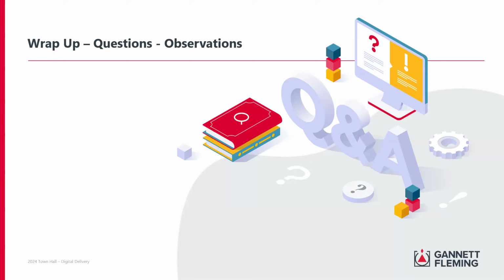Yep. One of those little pain in the butt things that I had to deal with all the time. Yeah, well, sometimes I've run into situations doing support for clients where they were grabbing stuff from a survey file and bringing it into Civil, but they didn't realize that things weren't lining up properly. Then they later realized that the INS units were different. Yep. The survey was different, and then their Civil was different. So eventually I had to backtrack, figure out what they were doing, and open up that survey file, and I noticed their units were different.